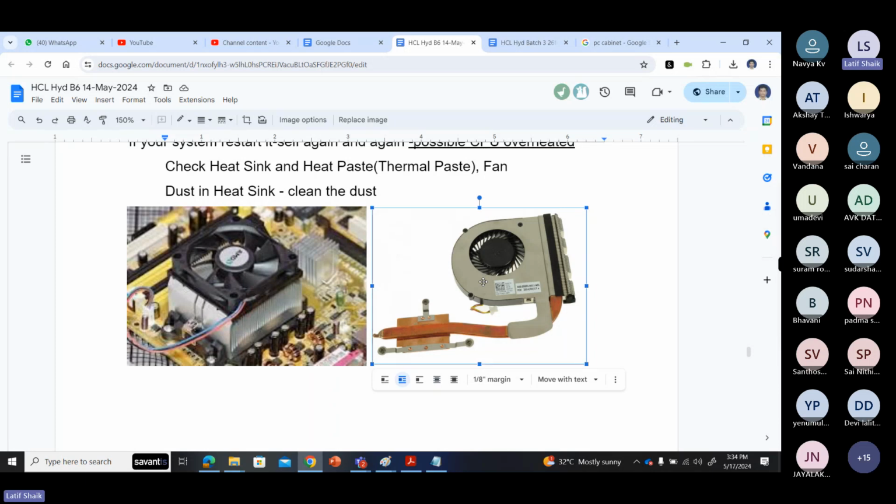If you see, there is a plate, a copper plate, and on the plate there is a copper rod. That is a heat sink. This processor is getting heated. The plate absorbs the heat and passes it to the copper rod, to that fan assembly. The fan is rotating, it is an exhaust fan. It means the heat will go outside of your laptop.